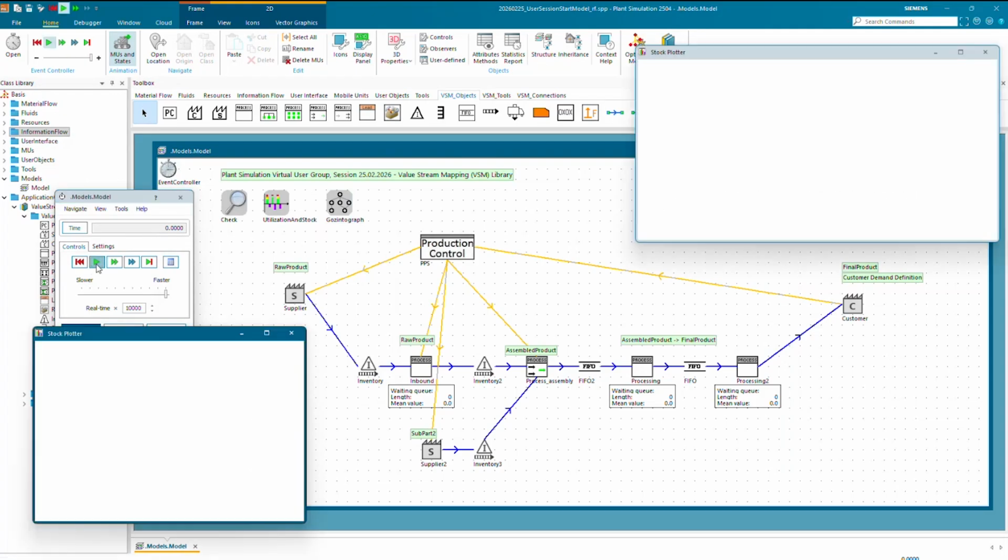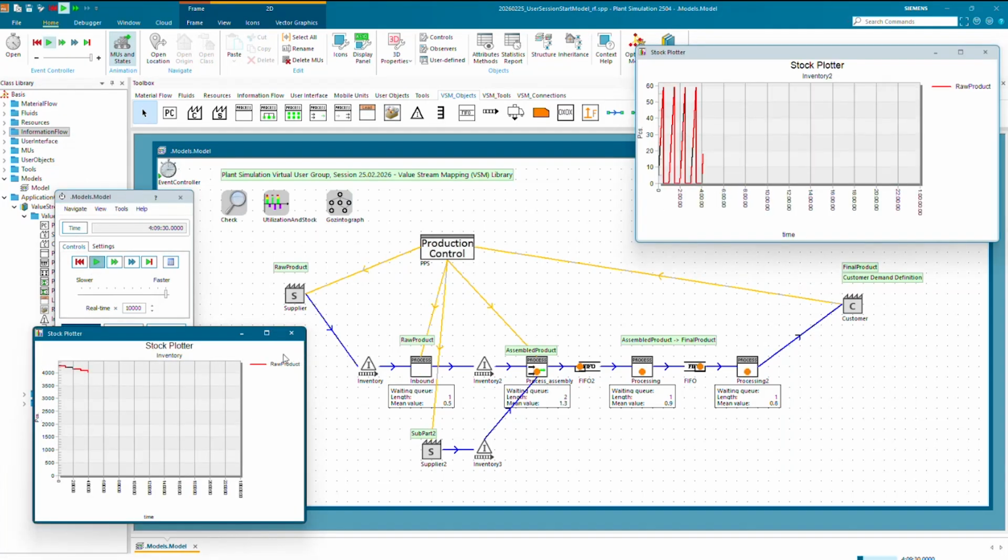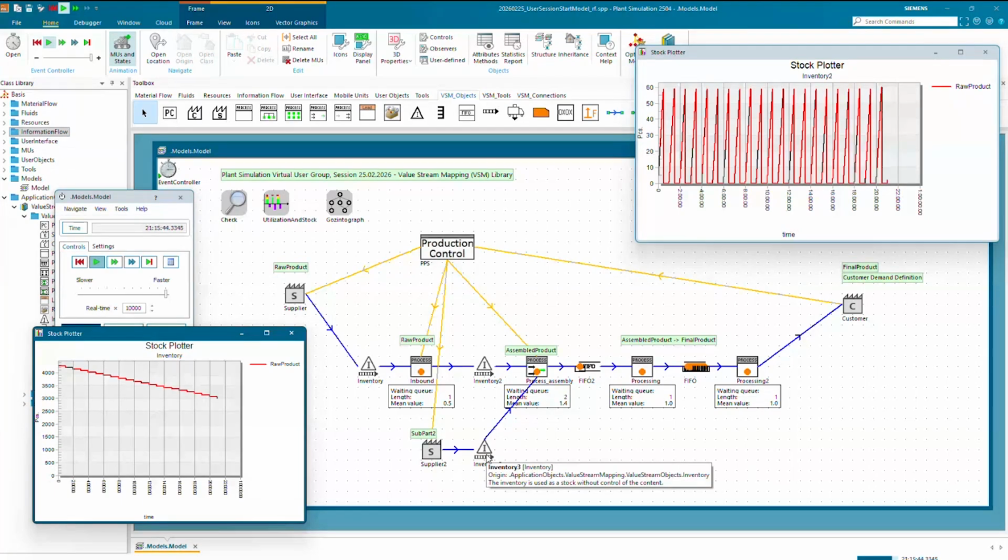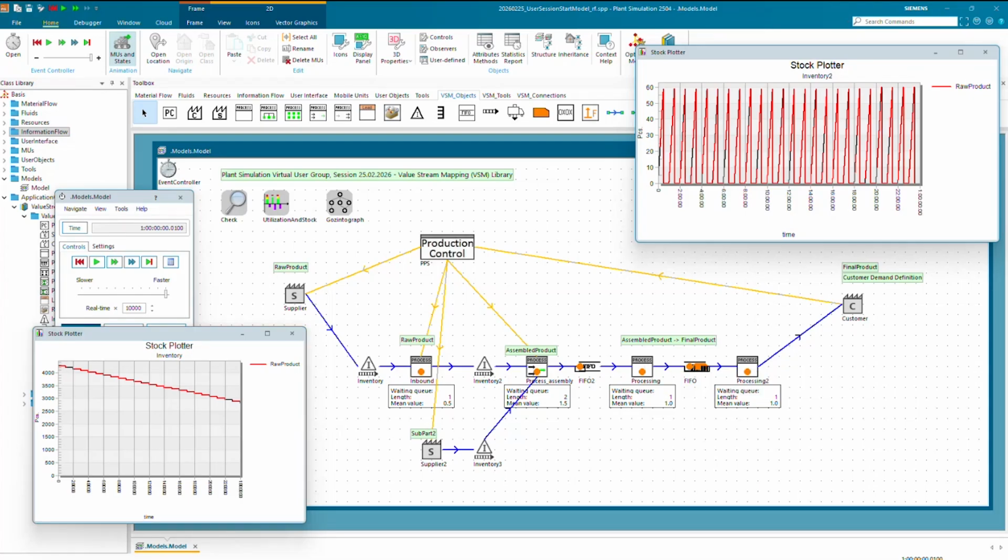And yeah, if we then model this and run the simulation there as well, the inventory right here would look the same. And what you can then add, for example, is processes here in the bottom. Once these processes are maybe too slow, you could change things up, so that you say, okay, this line might be too slow for a certain assembly. This line might be too slow. You would see it also within part statistics, or if an assembly is waiting for certain parts, or if a certain process is waiting for elements.